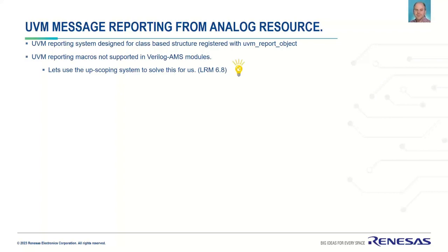So what I suddenly thought of is, hang on a minute, there's upscoping in the Verilog language, which means if it doesn't find a function in the local module, it looks at the next level up. So I decided, let's have a go at that. Let's see if it's supported. Does it work? Yes. Does it work all the time? It does work all the time, and all of this stuff we're showing today, we've got example code that has been tried on 3 main EDA vendors that participate.